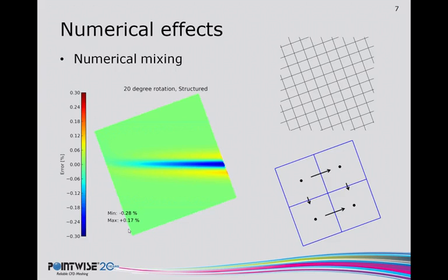Now, again, the error here is small. I'm not saying that you cannot sustain and cannot handle non-flow aligned cells. I'm just simply pointing out that these cells will introduce some error into your solution, and it's up to you to kind of mitigate those and decide whether or not that's going to be a large enough effect on your solution.